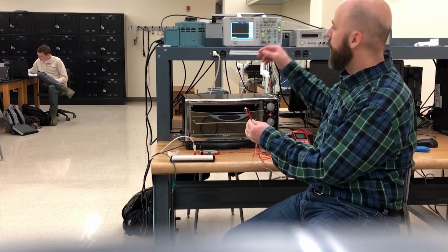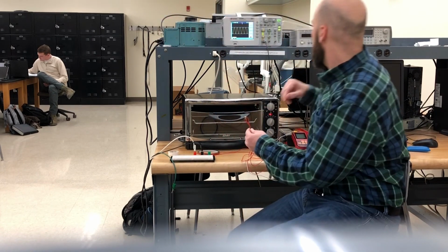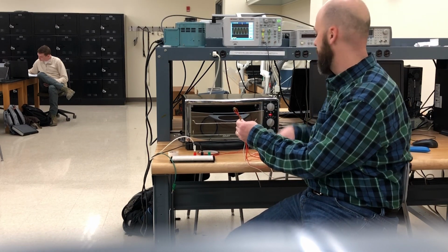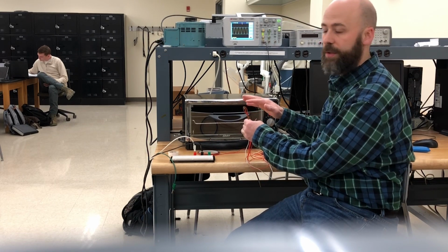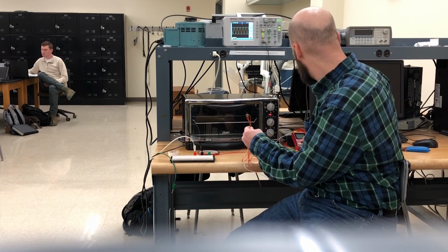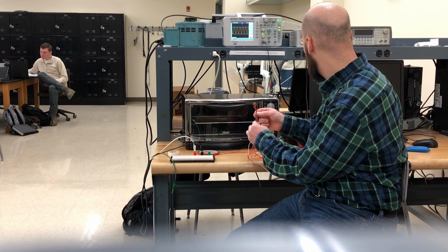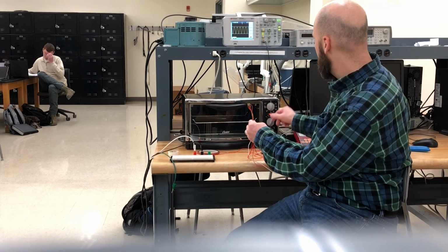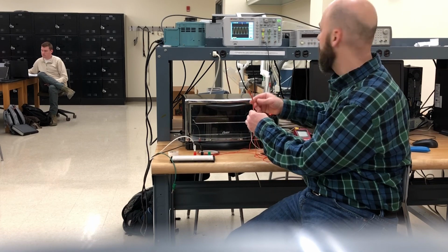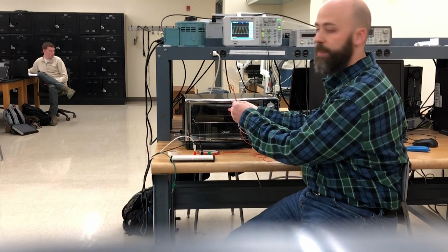We're going to start off with a full electrical threshold of the IC chip based on the spec sheet, which we have pre-set up here. So we have a maximum voltage and current, so it's at full load, and we let this warm up to an operating temperature. Our oven's also warming up. Then we're going to increase the temperature of the oven gradually throughout the experiment, monitoring the voltage, current, and temperature, and find the point where the IC chip actually fails. So I'm going to go ahead and put it in the oven now.